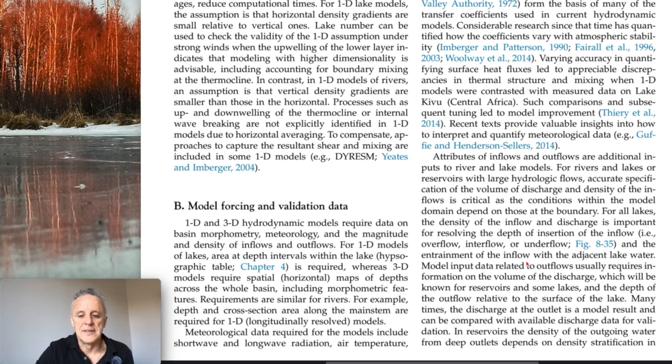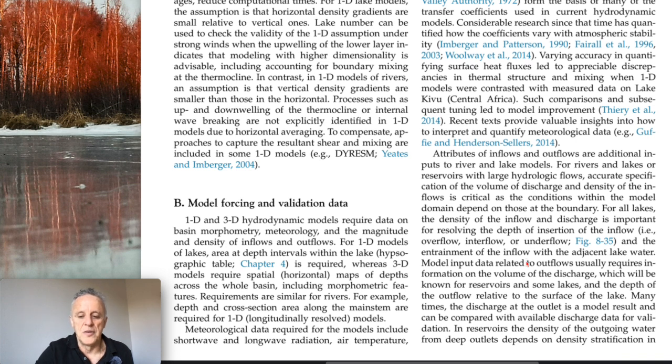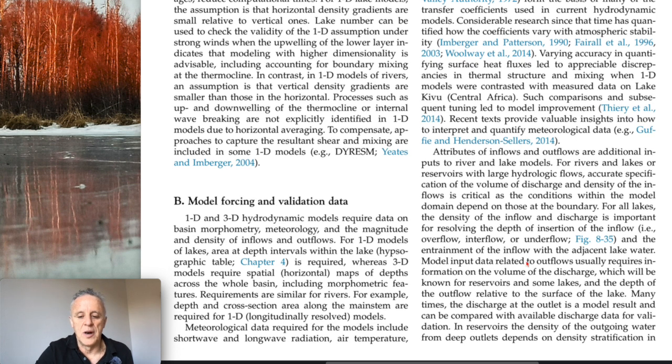For all lakes, the density of the inflow and discharge is important for resolving the depth of insertion of the inflow, overflow, interflow, or underflow, and the entrainment of the inflow with the adjacent lake water.